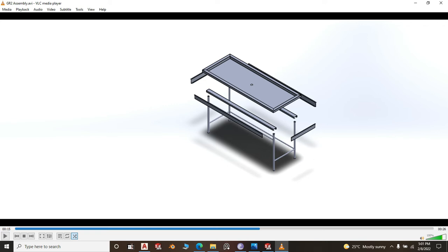Now once that is done and you have done your welding, you don't want these channels visible. They will look ugly. That is why you can see I have some pieces on this side, on the other side, and on the other side. These are what we call skirting. It might not be the right term. Some people might call it cladding, but I prefer skirting; I'm used to it. So you do some skirting to hide this channel. Also, if this was a receiving table for the dishwash area, you don't want the chute protruding from under here. You don't want people seeing the chute. So the skirting takes care of that.